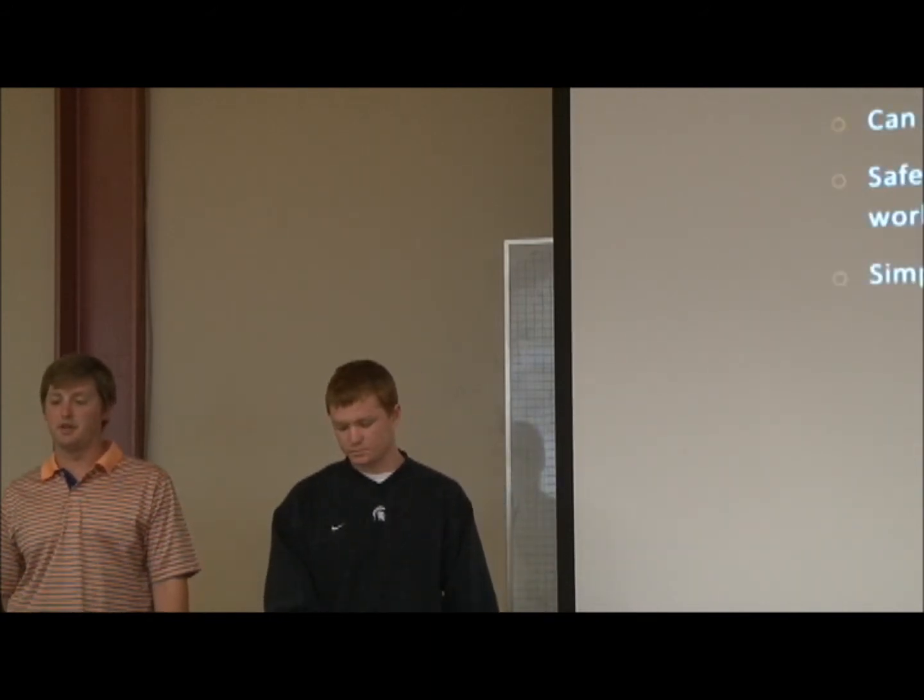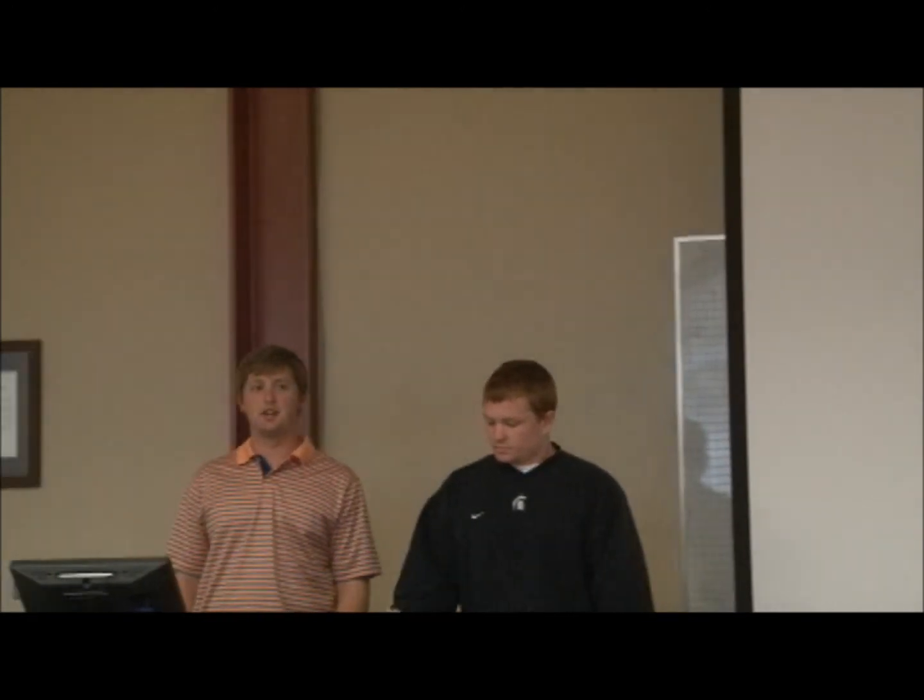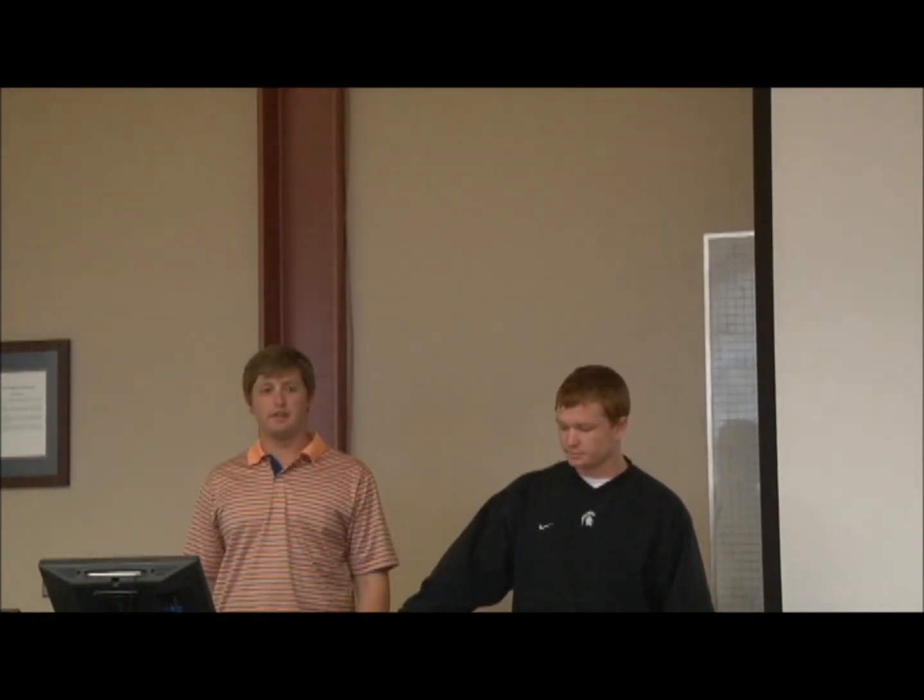Some of the advantages of 3D laser scanners is just like Terry just said, the time saving. It can be as much as 15, 20 times faster than traditional surveying methods. They can have a complete as-built model, which is very, very beneficial because it gives you a whole idea of what the entire thing's going to look like. And one scan only takes 90 seconds. So, like when they did the one downtown, it took one person less than one day to just scan those. And it's just very simple.